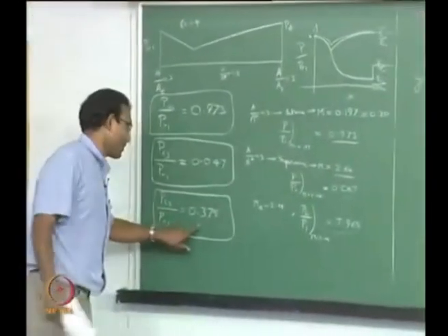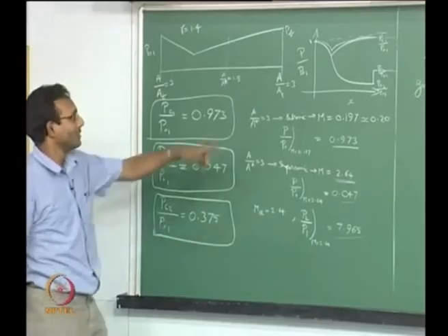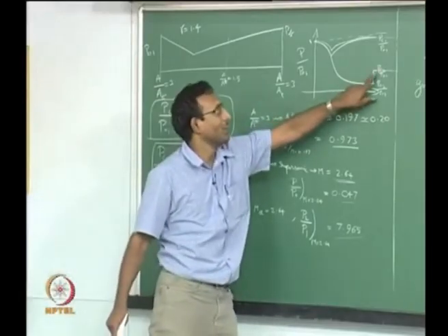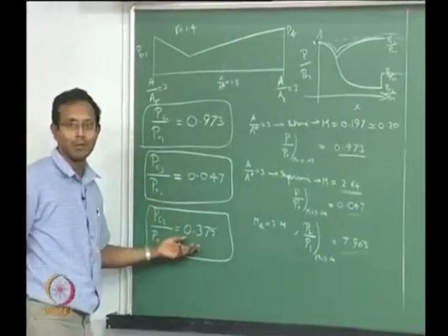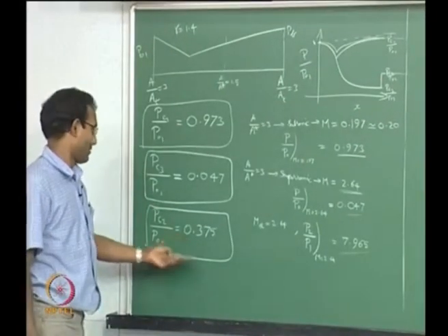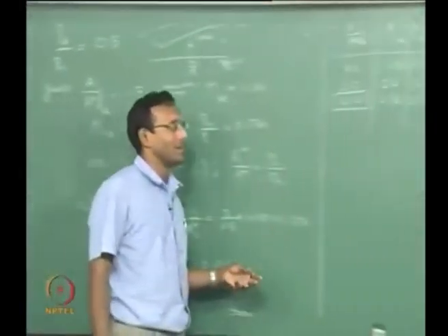If it is 0.25, I am in an over-expanded regime. Remember, it's below P critical 2. I cannot use 0.25. So choose, say, 0.6 and solve the problem again. Okay, if I choose 0.6 and I want to solve the problem again, new problem, P exit by P naught